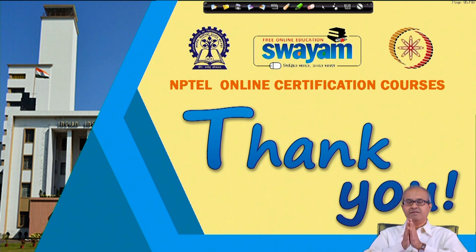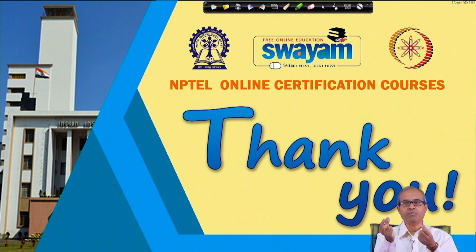So, we have seen in a nutshell the various kinds of instructions which are there in ARM and the unique features. In particular, I have talked about the conditional execution in this lecture. Earlier we have seen in terms of the arithmetic and logic instructions, when you are executing, the second operand can be specified in so many flexible ways. So, there are many ways in which you can make your code shorter by taking advantage of these flexible methods, then the multiple register transfer instructions and so on.